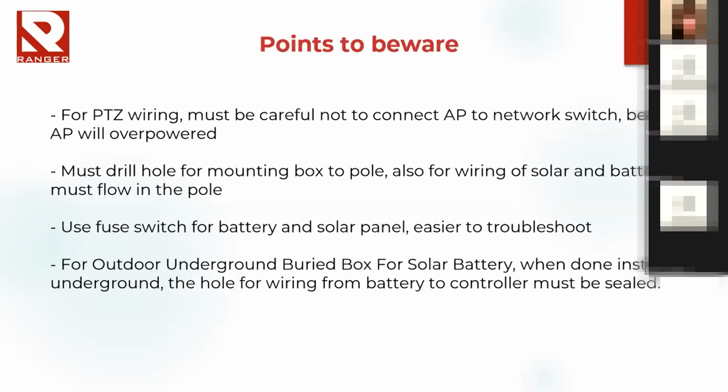Then I move to points to beware, which is the PTZ wiring. Must be careful not to connect the AP to the network switch, because the network switch is 48 volt. The access point that will be used is 24 volt, so it cannot be connected directly to the network switch. Must use a PoE injector, or else it will be overpowered and burn.